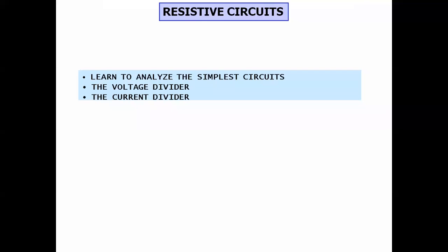We also know that the division of voltage depends upon the value of the particular resistance. If the value of resistance changes, the voltage division will change. So the voltage drop across a particular resistance depends upon the value of resistance. Why is it independent of current? Because in a series circuit, the current remains the same. So we can use the voltage divider rule in the analysis of a series resistive network or series circuit.